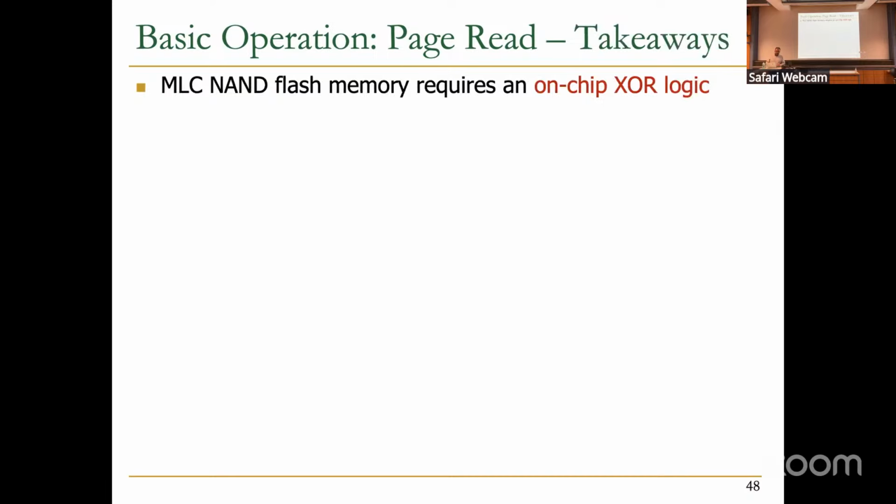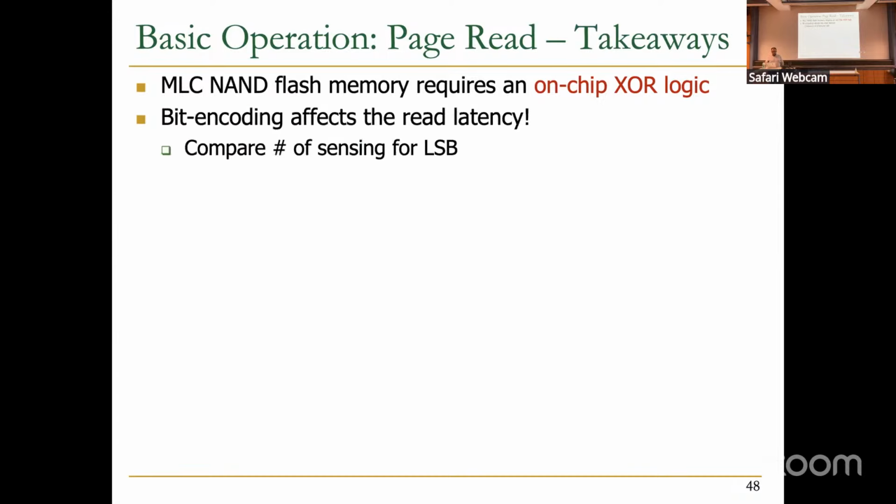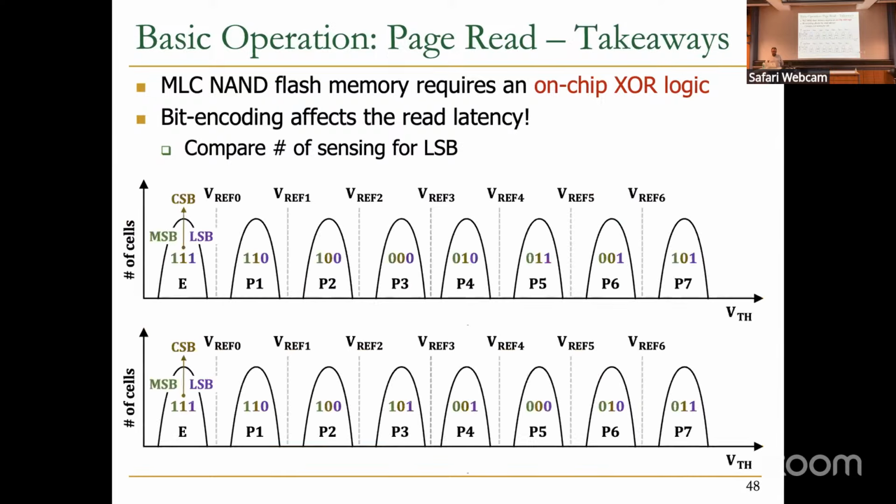So that's why in MLC NAND flash memory, we actually have on-chip XOR logic internally, and so it's already implemented. But you can also see that bit encoding affects the read latency. So we can do some game here together. Here I'm showing 2 encoding schemes. The top one is the one that we had in the previous slide, and the bottom one is something else. It's a bit different in how you encode these states.